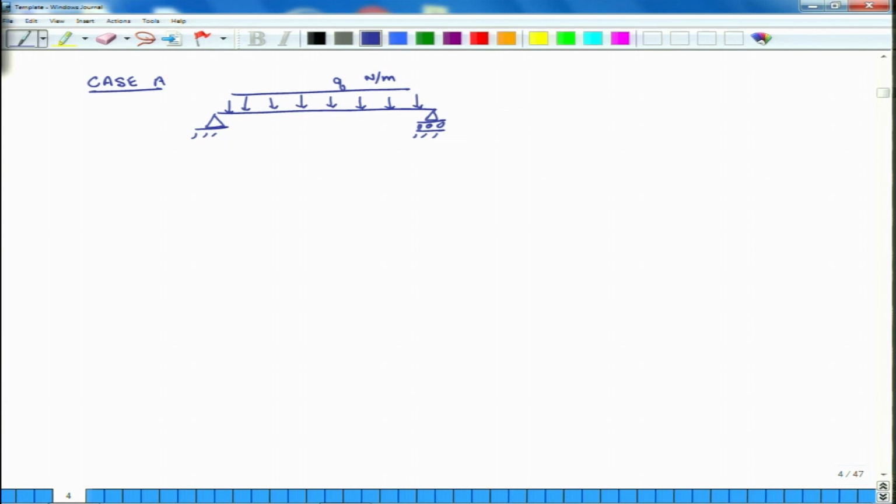The boundary condition here is U minus equals V minus equals W minus equals Mx minus equals 0, and in the other case it is Nx plus is equal to Nxy plus is equal to W plus equals, so these are all mid plane displacements, equal to Mx plus equals 0, and the lamination sequence is 0 to 90 symmetric. That is the lamination sequence.